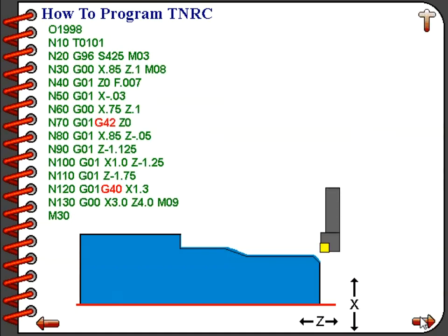To handle this, because it is such a common problem, because we take a turning tool and we will often face the part first and then come in and perform our finished turning operation, I've demonstrated to you in this program how this is handled, and it is truly quite simple and elegant. What we will do, between line numbers 10 and 30, we'll have our tool startup information, positioning the tool ready for the facing cut.